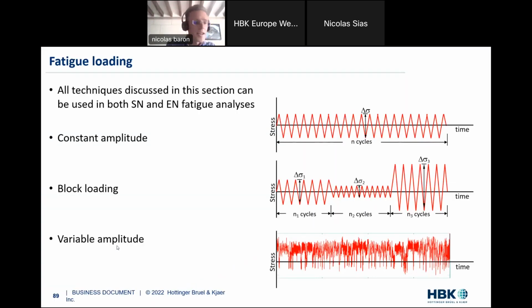So again, on the fatigue loading, we have seen before these kinds of loading. I've explained Miner's rule, and now let's focus really on the variable amplitude loading, the one you have here. The goal is to have some cycles, right? But here it's very difficult to see the cycles. Which are the cycles here? When we just look graphically at this recording from the measurement, from our measurement colleagues, we don't see any cycles. So how can we find out the cycles contained within that signal?